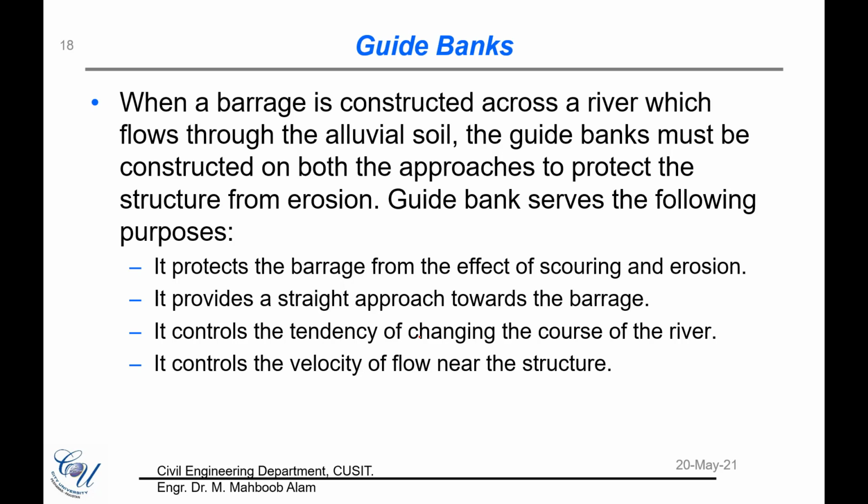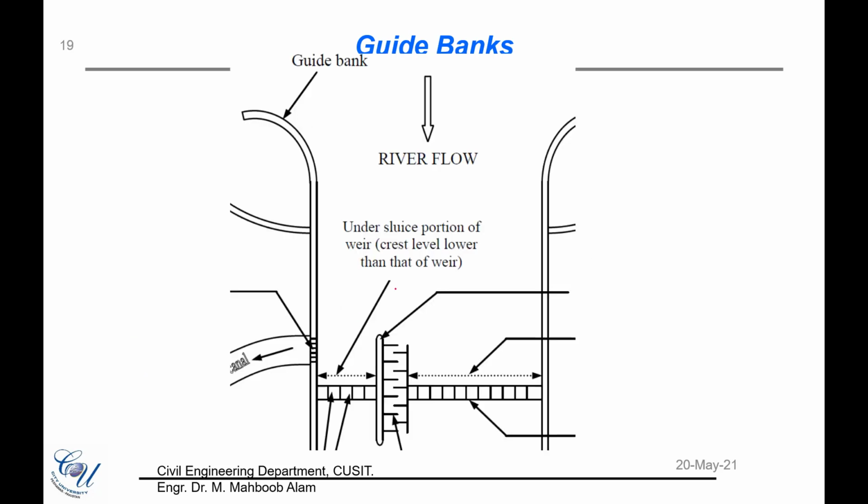So the guide banks ensure that the course of river is maintained in a particular section of the river which is needed. So this is also an important function of the guide banks. And as I said earlier, the velocity is also maintained by these guide banks.